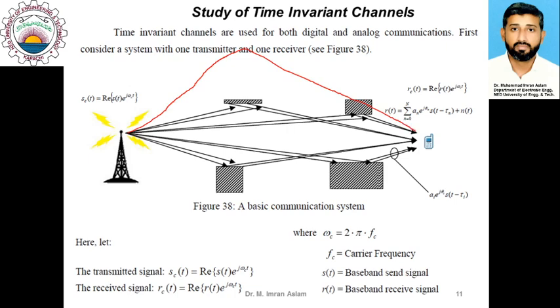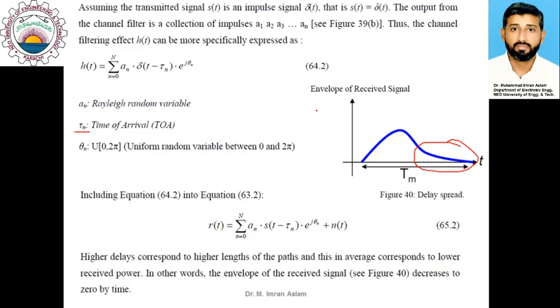If a signal is covering a longer distance, this time would be large, and because it comes from the longer path, the wave experiences a high amount of loss. So received power is generally small. You can see that after a certain time this received power is significantly small, and you can ignore the power after a certain time duration.